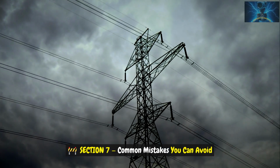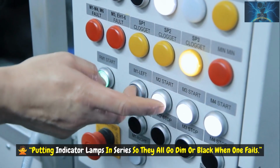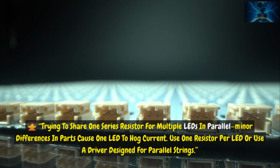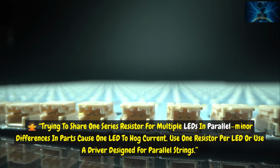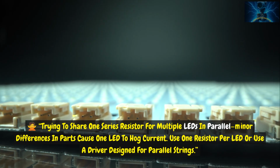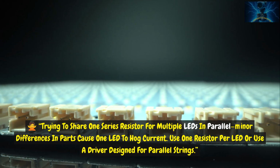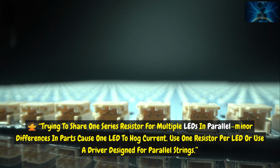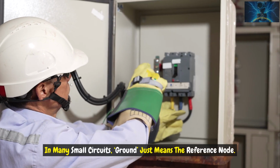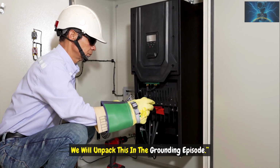Section 7. Common mistakes you can avoid. Putting indicator lamps in series so they all go dim or dark when one fails. Trying to share one series resistor for multiple LEDs in parallel. Minor differences in parts cause one LED to hog current. Use 1 resistor per LED or use a driver designed for parallel strings. Assuming ground is always the dirt. In many small circuits, ground just means the reference node. We will unpack this in the grounding episode.